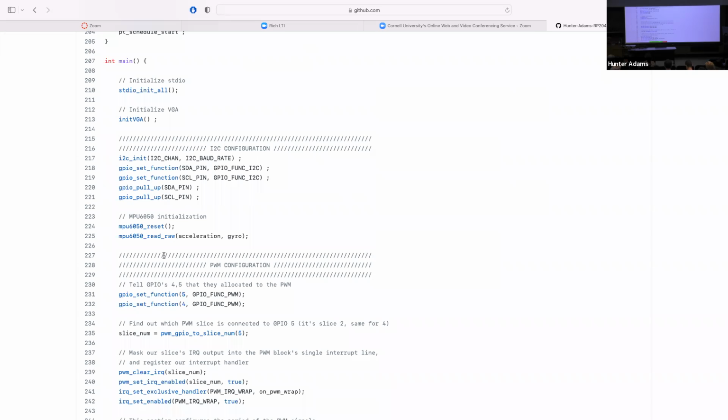And I'll remind you again that on an I2C channel, there are 2 lines. One's a clock line, one's a data line, and both have pull-up resistors attached to them. And the recommended starting point for those pull-up resistors is something on the order of like 4 to 5K. And what I said last time is, well, just turn on the pull-up resistors associated with these 2 GPIOs to which you have the I2C channels connected, and then you don't have to breadboard an external one.